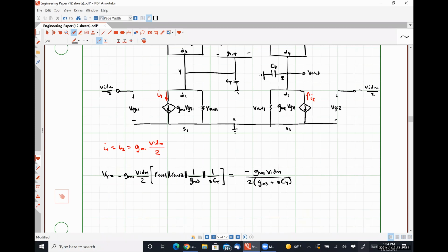So these two guys in parallel means that their reciprocal conductances are in parallel, and conductances in parallel have like resistances in series. And then I just use the 1 over bit because it's 1 over the resistance. Or we could do it the long way and actually do math, but that's much easier and you get the same result. Okay. So that's what Vy looks like.